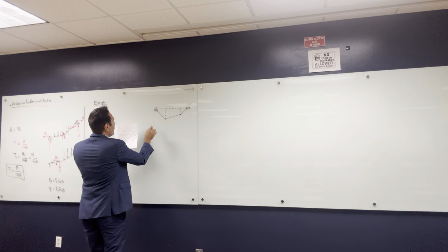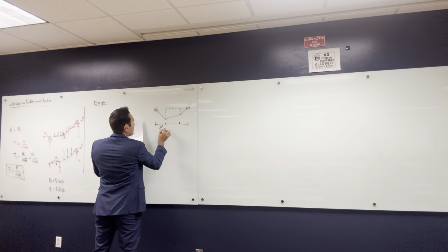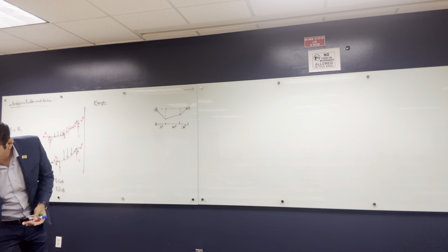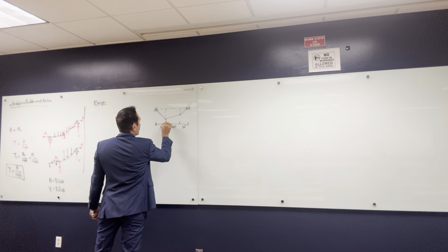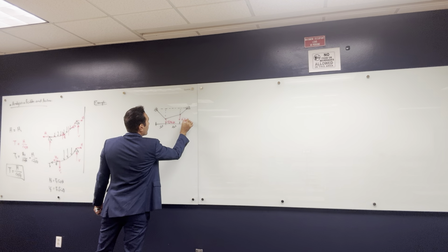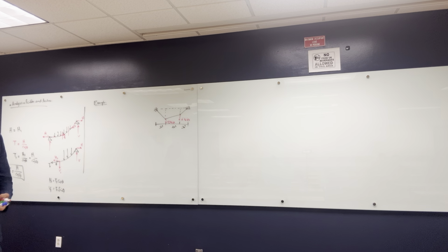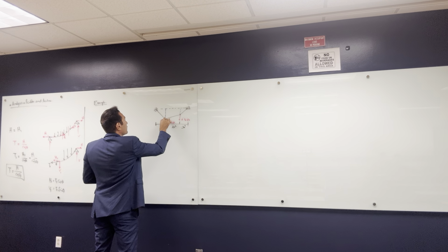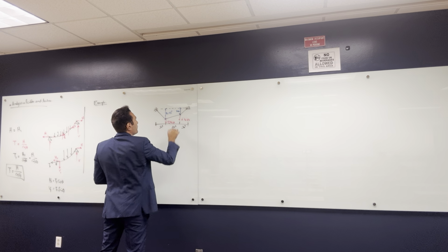All right, I have this cable. The distances are 30 foot, 40 foot, and 30 foot. And there are two loads on this cable: a concentrated load of 12 kips, kilopounds, and another one of 6 kips here. I gave you H1 here, which is equal to 6 foot, but I didn't give you the value of H2.